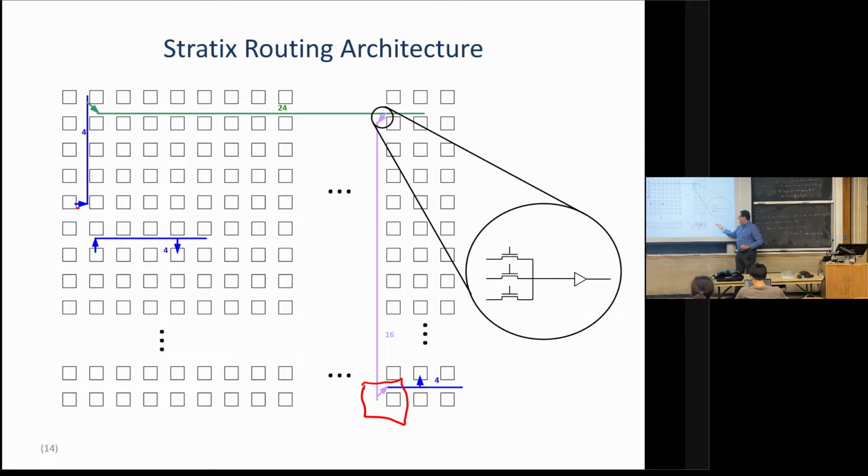For that to work, you need to have a repeatable pattern. So for a repeatable pattern, this has got a length 16 wire in it. What you can do is say one length 16 wire starts here, so there's one direct drive switch. And a different one will start at the tile above and so on. But basically, you couldn't have 12 of these, right? You could have 16, where you say one of them starts in every single tile, and I'll lay out a tile where that happens. You could have 32, because you could say two of them start in every tile. But I can't have 12, I can't have 17, etc. And yeah, that is a restriction.